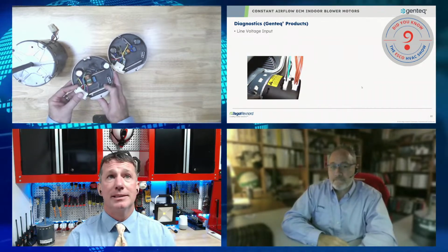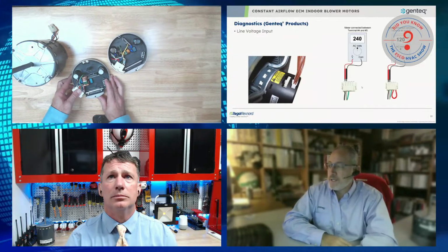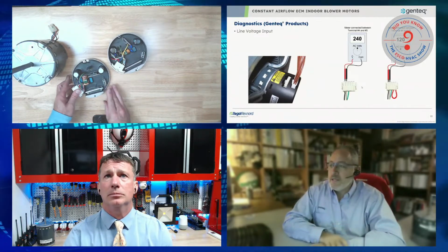Yeah, I had a brand new piece of equipment that I went and did a site visit on that was verifying voltage. And I said, well, let's pull that plug off there and just check all of our pins first. And we actually found one that had actually pushed itself through. And so, yeah. So we want to turn the power off, and we want to check the pins that touch the motor.